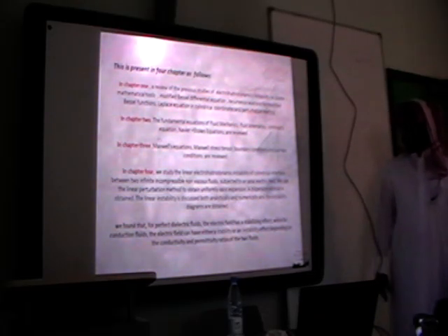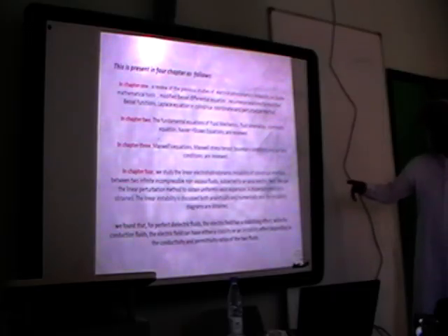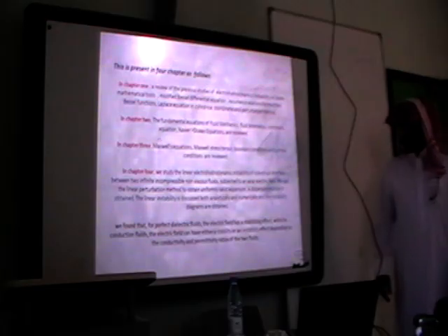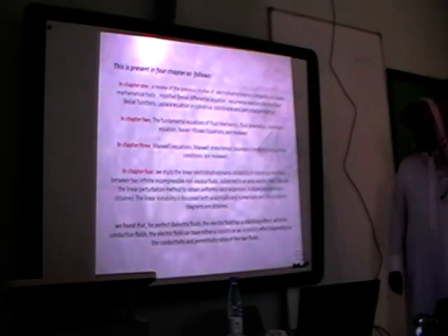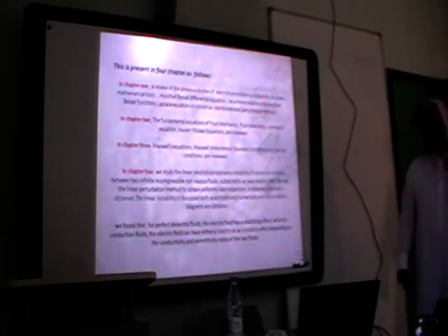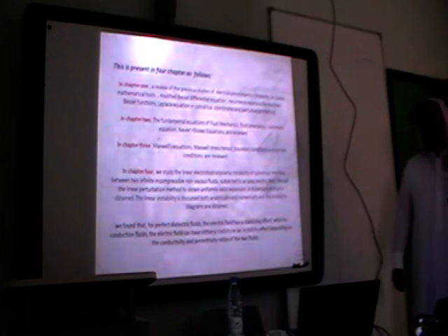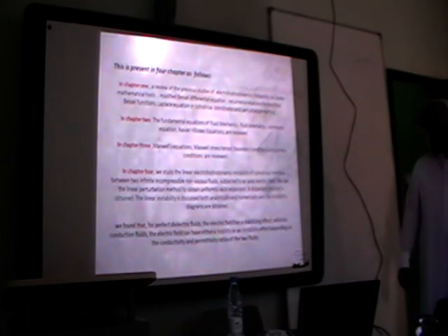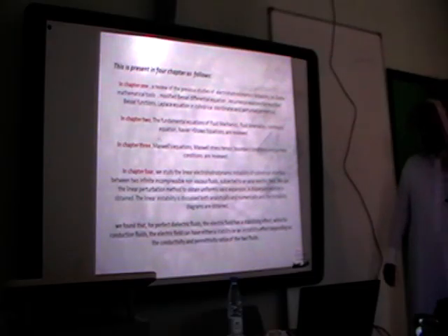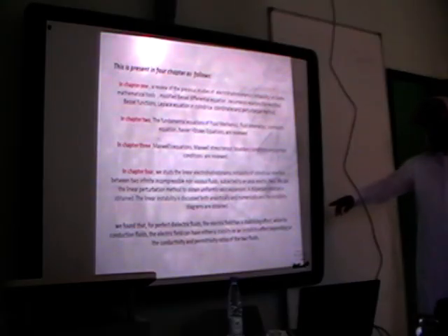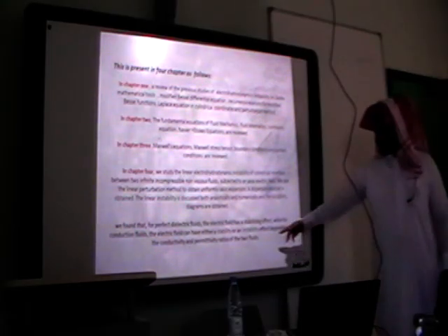And the instability diagrams are obtained. We find that for a perfect dielectric fluid, the electric field has a stabilizing effect, while for a conducting fluid, the electric field can have either a stabilizing or a destabilizing effect, depending on the conductivity and permittivity ratio of the two fluids.